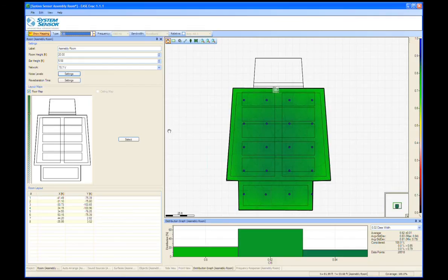Does this program address sound transmission across construction barriers, i.e. walls, or only within single enclosed rooms? That's a very good question. All the predictions are confined to within a single room. There's no transmission through walls within EVAC. Everything within a room happens within that particular room. There can be no doors or windows in rooms that allow sound to leak out or in.